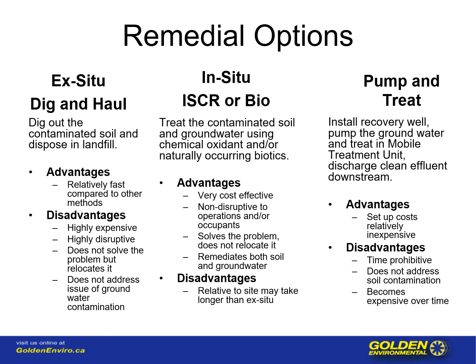Now, the calcium hydroxide portion of this mix of amendment will continue to oxidize for about 9 to 12 months. This is ideal in that it slowly releases oxygen, helping the aerobic degradation of the contaminant by the microbes.